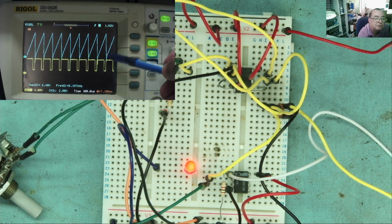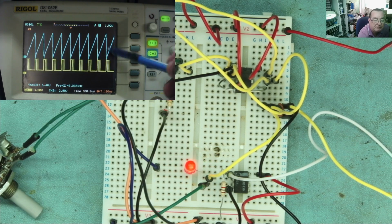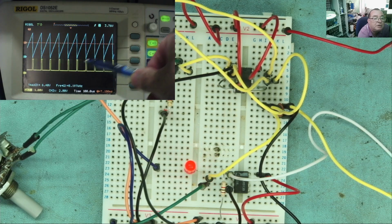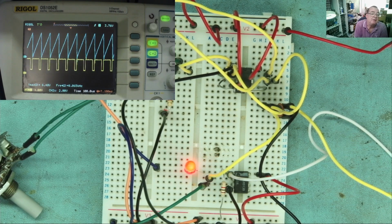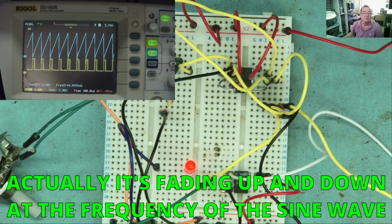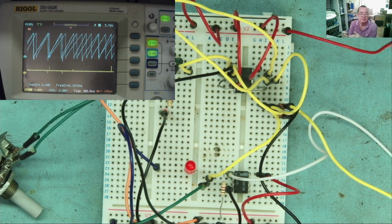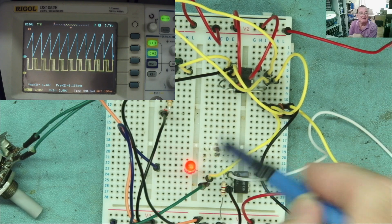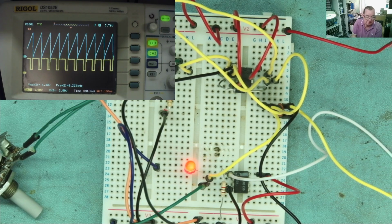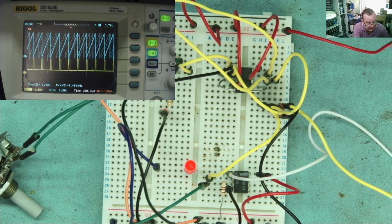I'm sorry, my scope is just losing synchronization occasionally, even though I try to set a trigger, but we won't worry too much about that. And the yellow one, you can see the pulse width modulation there running from effectively 0 to near 100% duty cycle. Okay, and if you look at the LED, you'll see it's flashing on and off. So the data, which is the changing voltage, is being sent to the LED via the carrier, the 8 kHz sawtooth. Okay, let's go down a little bit lower in frequency again.